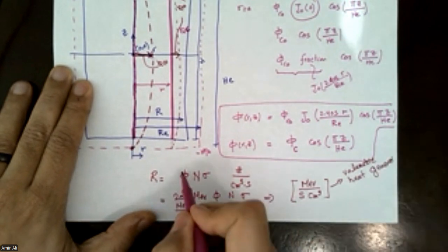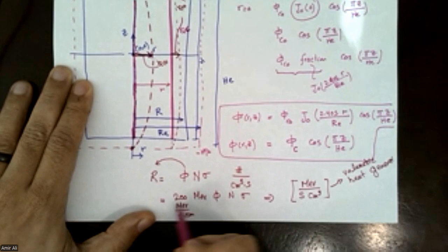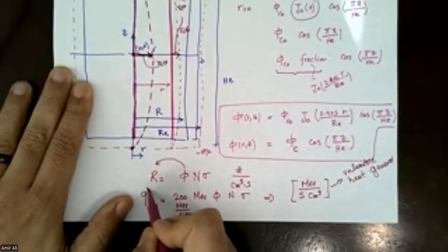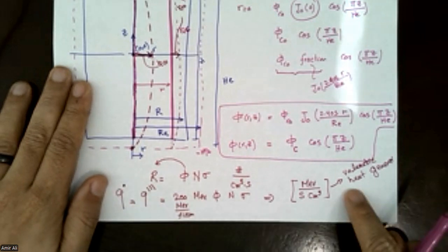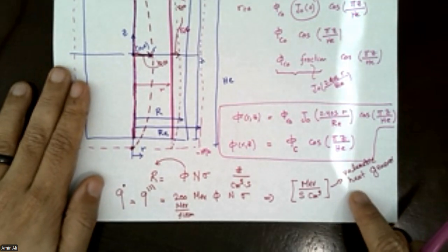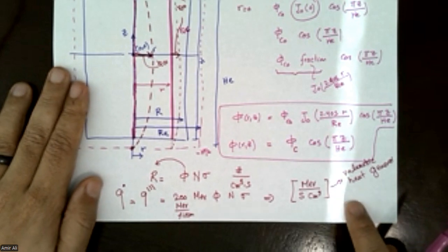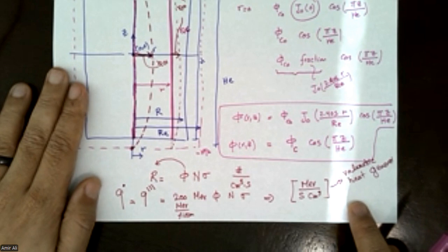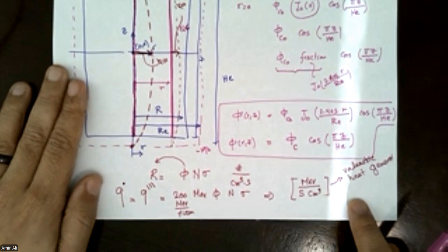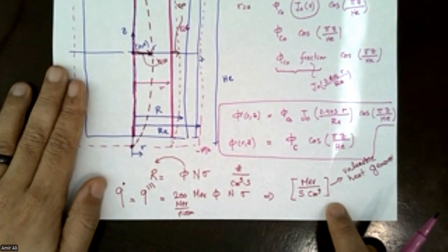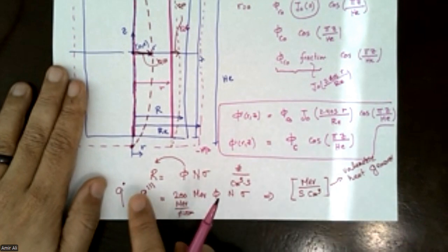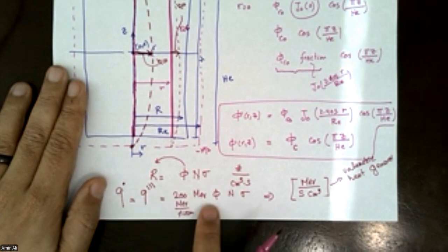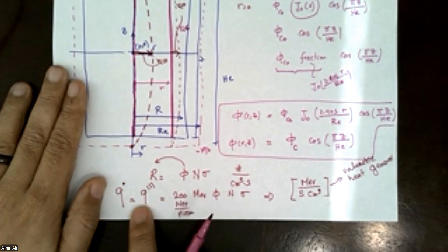And this is how we're going to convert the neutron flux into Q triple prime or Q dot. You guys remember from the heat transfer basics? Q triple prime is a volumetric heat generation, or the volumetric thermal source strength, or heat generation per unit volume. Call it whatever you want. The unit is telling me that I can convert that reaction rate into heat generation. If I integrate the neutron flux, I can integrate the Q triple prime.